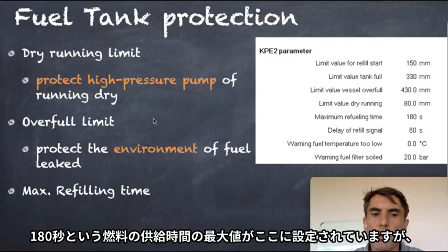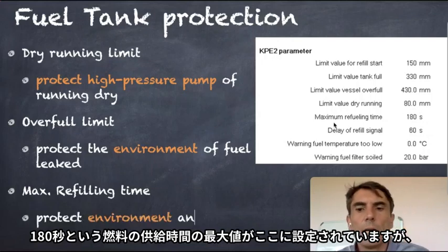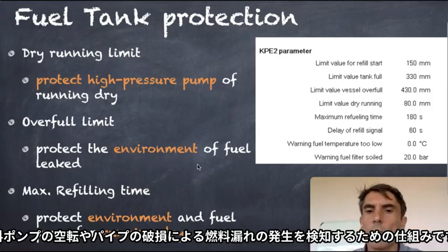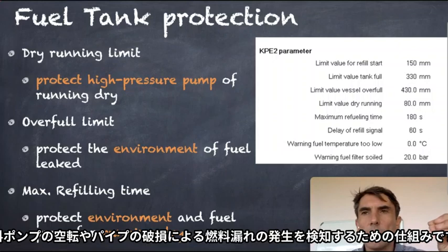And we have a maximum refilling time, 180 seconds. This is to protect, on one hand side, the environment. For example, if we have a leakage or a broken pipe after the refilling pump, the pump will run and the level in the tank will not increase.